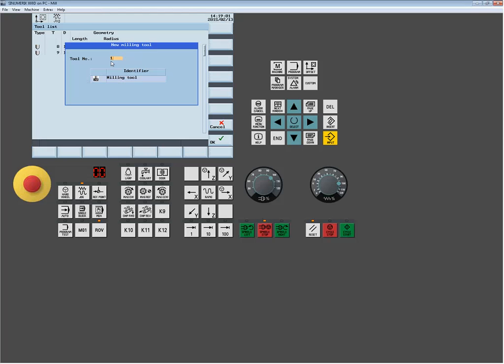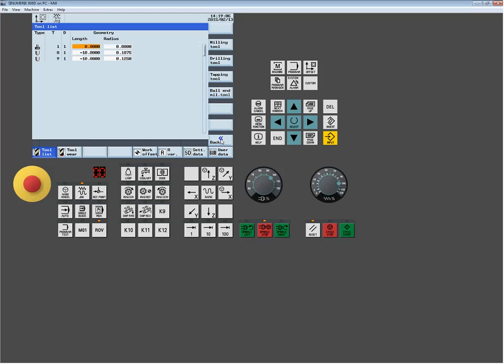and I'm going to zoom in. You're going to start to see the machine come around. It's applying some form of cutter compensation. Okay. Now, this is the first area that you have to start to pay attention to when you roll around the cutter comp. What's happening right now, and what you don't know, which I already know because obviously I methodized all this stuff, is that we think that this machine should be running tool 1.